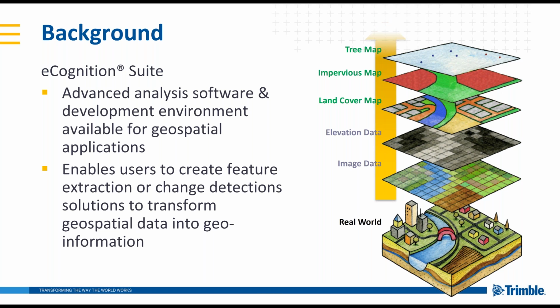Transform these very nice data products into geospatial information, and by that I mean extracting out the information and putting it into, say, a land cover map, an impervious surface map, or maybe even looking at specific objects within our imagery, such as individual trees, manhole covers, something of this nature. This is what this software provides the tools to do. You can think of it as a toolbox for creating image analysis workflows, what we then call rule sets.